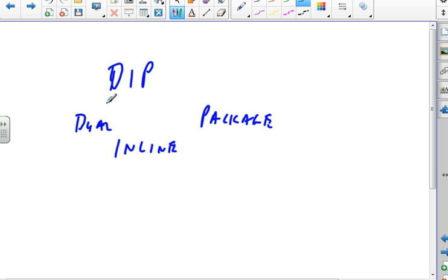Well, the problem is that the switch is right at the interface between hot and cold. The cold of the refrigeration going on and the hot of the outside. So it was always in a moist condition, and it failed often.